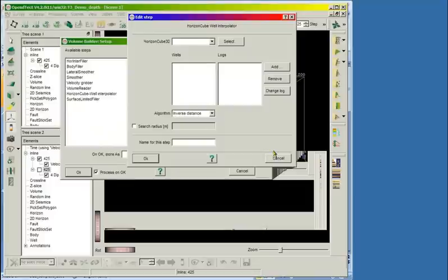This gridding step will take well logs and will grid well log amplitudes in order to create a new 3D volume. These well log amplitudes could be DT models loaded as logs in the OpendTect wells. And they will be interpolated between the wells by using inverse distance or triangulation algorithms. For wells, most often inverse distance will be the one solution to use.